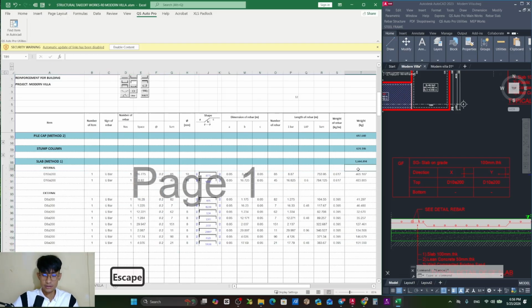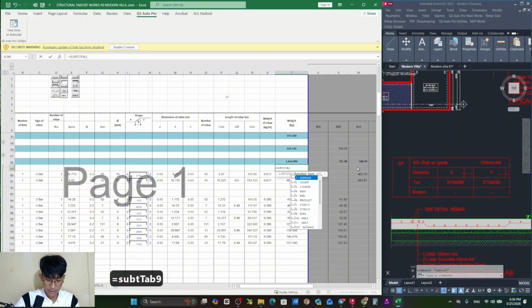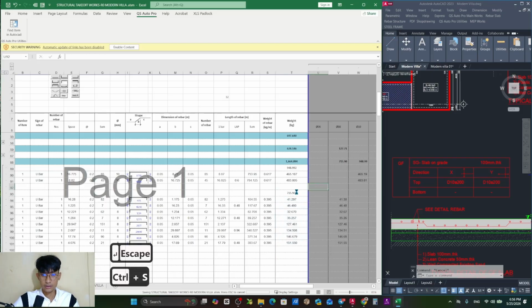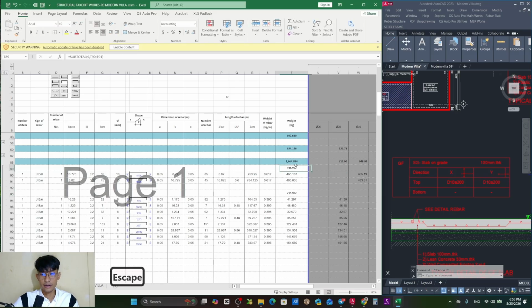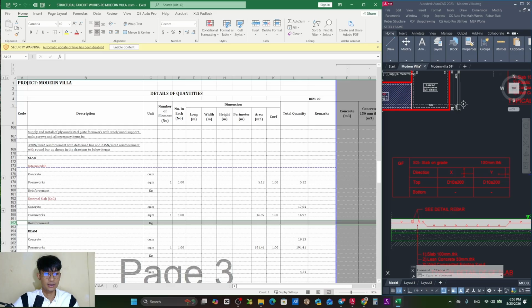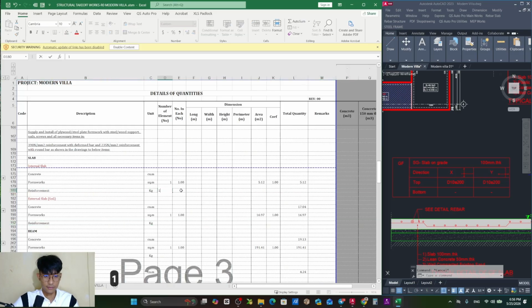Perfect. So now let me subtotal this, because there will be inside and outside rebar slab. Okay, so we split it into 2 types. Okay, perfect. Just use subtotal, do not use sum in here in case to avoid the error. All right, so the total here is 1.6k. Okay, perfect. So now we link it to the front, and you can see for the external and internal. So we go for our format as usual, and equal to the internal one, 948 kg. You can see.